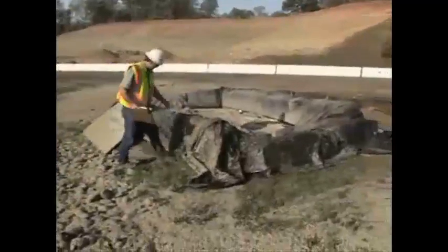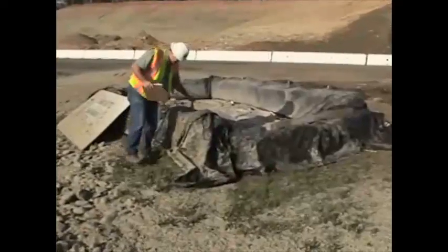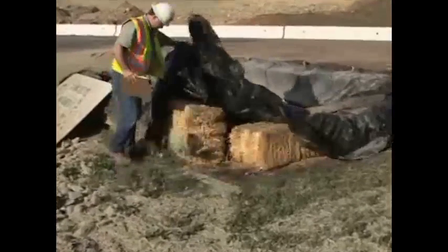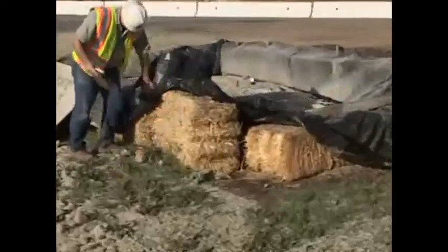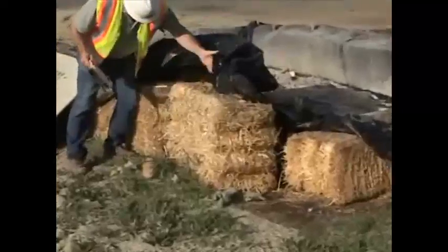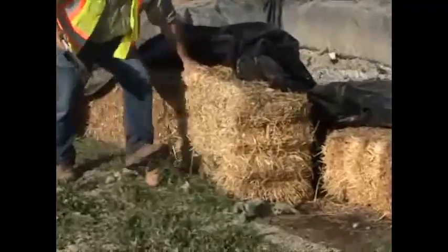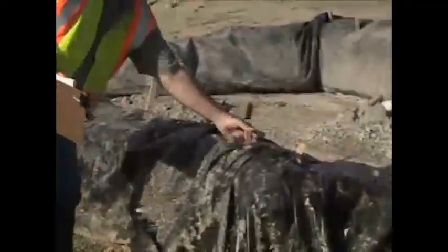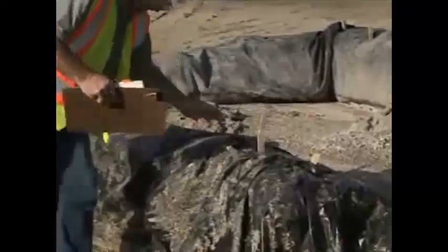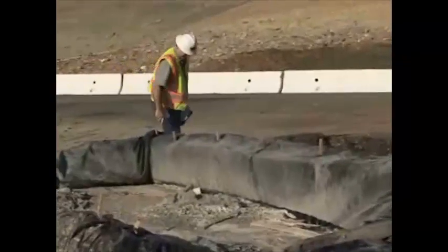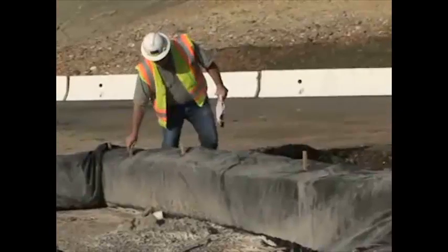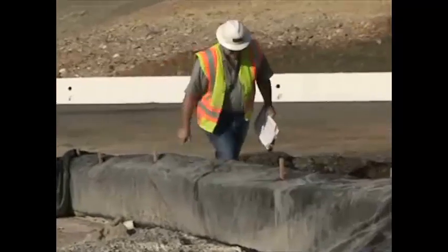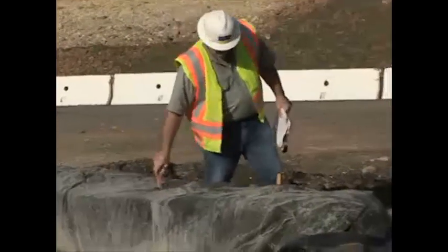Straw bales stacked at a maximum of 2 bales are situated along the perimeter of the washout facility. Straw bales must be a minimum of 14 inches in width, 18 inches in height, 36 inches in length, and shall have a minimum weight of 50 pounds. The straw bales are anchored in place with wood or metal stakes. The stakes must be a minimum of 4 feet in length. The project special provisions require that the contractor install 2 stakes per bale.